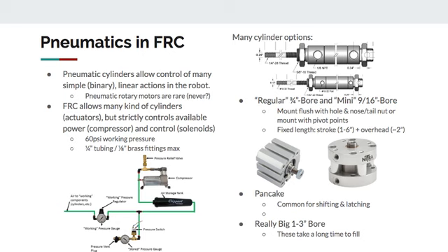But if you wanna be even more efficient with how much metal there is behind it, you can get these, so the 9/16 bore isn't even that small, but it does cut the weight of the cylinder about in half for the 1 inch of movement. It also makes the cylinder a little bit shorter because the end caps aren't as big. And then they make, I think I saw maybe a 1/4 inch bore or something on a robot at SVR this year. That's probably a little bit smaller than is worth it because there's not that much force that comes out of it.